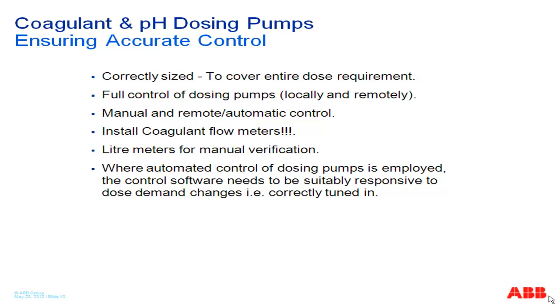And the last word there, where automated control of pumps is employed, the control software. Sorry, a bit long-winded. What I'm trying to say is the actual pump control, if it's using 3-term technology, PID technology, needs to be suitably tuned and responsive to the requirement, i.e. as things change, the pump outputs are changed to drive to that set point, and it's controlled nice and tightly, i.e. you don't get big swings up and down and it takes forever to get to the set point. So just thought that needed to be put in there.